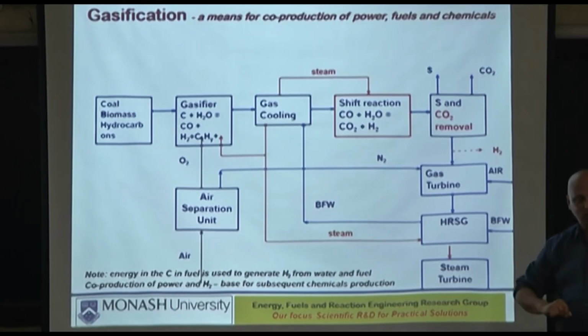The problem with too low a temperature is it is a kinetic process, so the rate will slow. And if the rate slows, the reactor has to be very, very long, very large. So there is a delicate balance, and where is the balance? Around 300. That's more or less universally accepted these days, that you get just enough rate and just enough conversion.